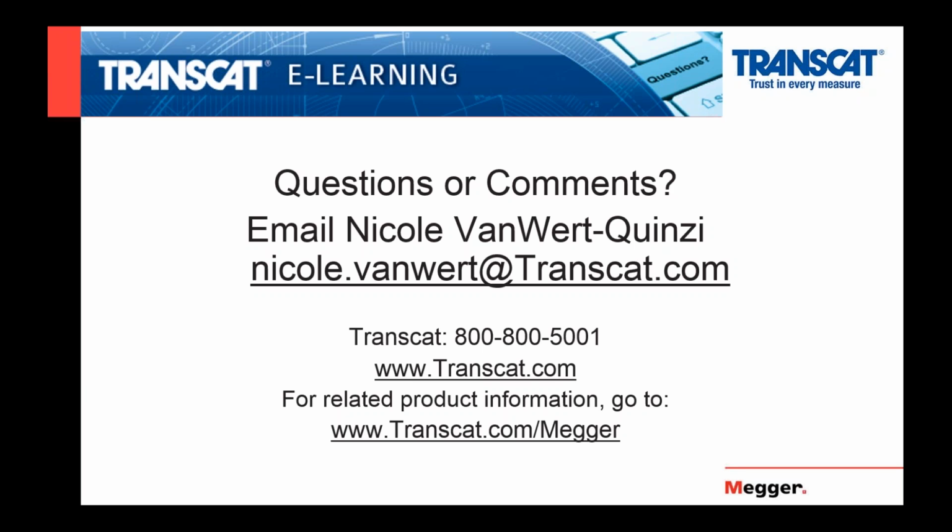Okay. Now, how is battery capacity defined? What is meant when you say a battery has failed to reach 80% capacity on a discharge test? Oh, what they're looking at there is the battery is defined by its 8-hour rated capacity on its data sheet. So if it's rated for a certain amount of capacity, that it should reach over an 8-hour period.